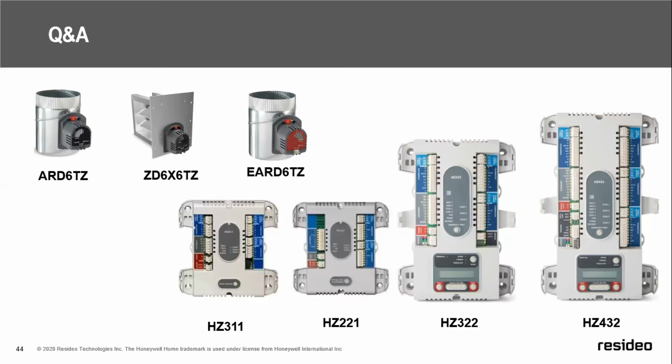Well, our dampers default to the open position, so now you're sending all the humidity to all the zones if none of them are calling for heat, instead of just dumping 22 gallons of humidity into zone 1 and satisfying that thermostat's call for humidification in a New York minute, to use some of the nomenclature we don't talk about down here in the South. Okay.